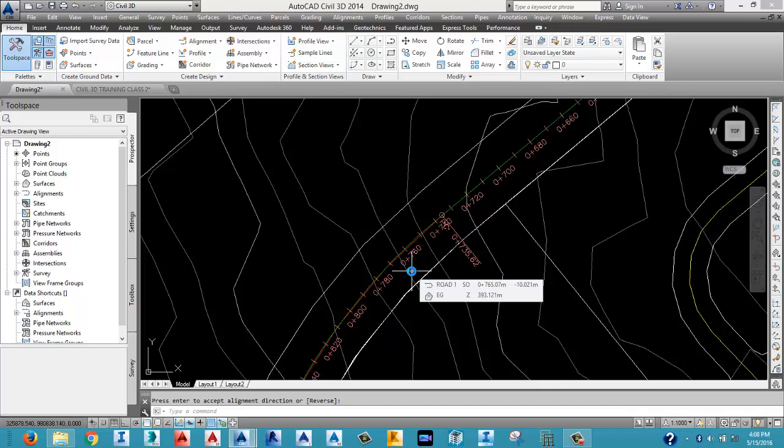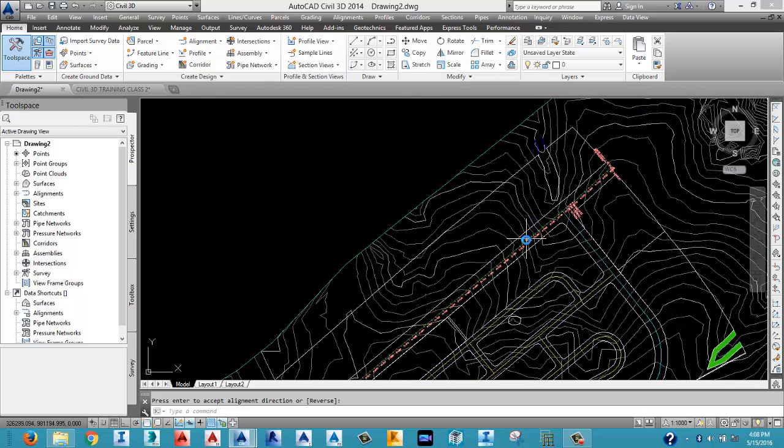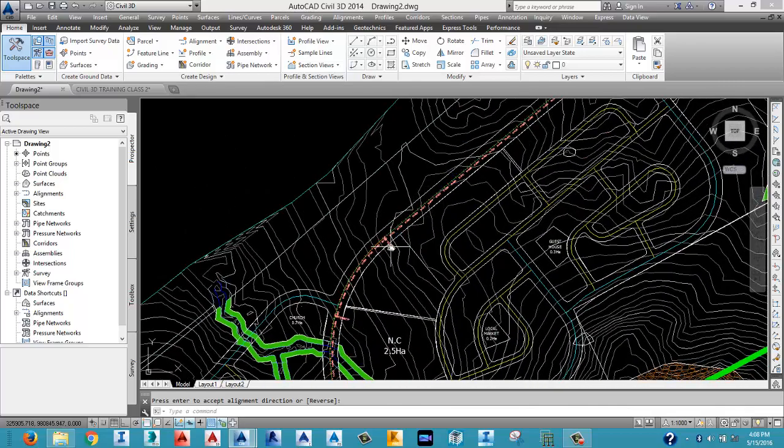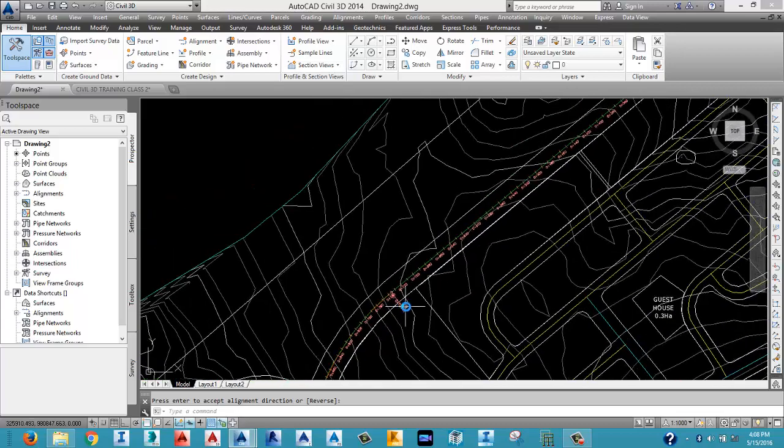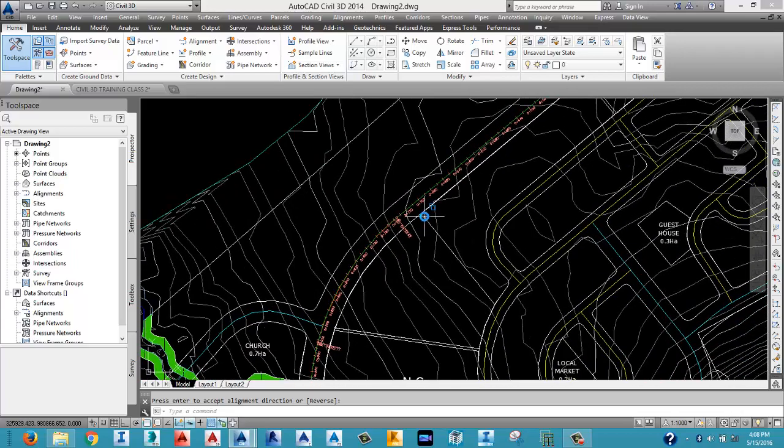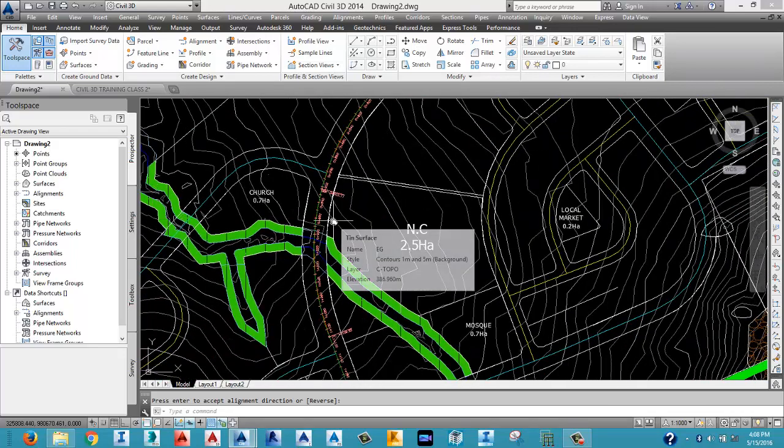You are running at 80 and you are enjoying the speed at 80 along this road. You can't keep that 80 speed once you get to this bend. You actually have to decelerate. But if I should design this road with 80 km/h, the curve settings would be designed along with 80 km/h so that I can maintain my design speed once I approach the curve, and I won't feel any negative impact of maybe skidding off or anything.